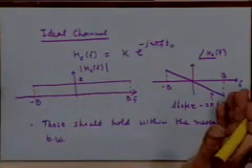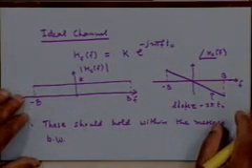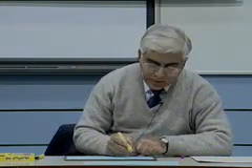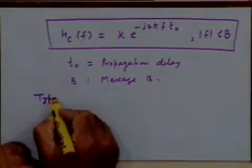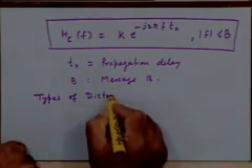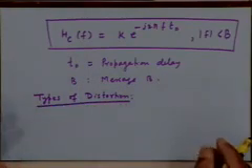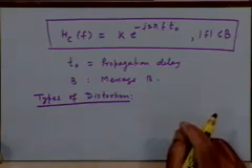For the ideal case, what is the impulse response like? The impulse response is an impulse function, right. That is why whatever signal you transmit, it gets in the same form to the receiver, right. Okay, but in this case it will not be so if these conditions are not satisfied. So what kind of distortions can be introduced? So let's discuss types of distortion. Incidentally, these kinds of distortion that I'm discussing here, we also refer to them as linear distortion, right.